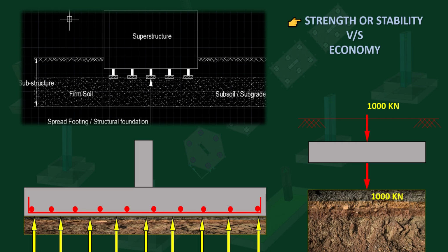So the question is, what for we are going to design our foundation, what for we are going to provide the reinforcement in the foundation. We are going to provide the reinforcement, and the sufficient depth and sizes of the foundation for the purpose of resisting whatever load your soil mass is going to exert over the base of your foundation. Whatever the pressure, whatever the upward stresses going to be exerted by the soil mass to the base of your foundation, for that we are going to design our foundation.